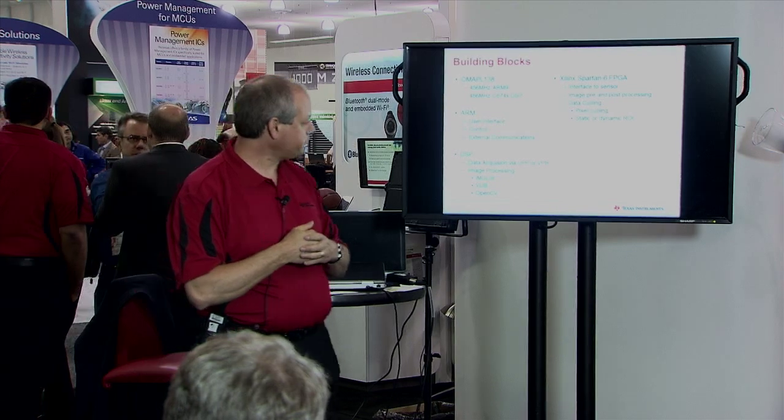So you can run about 150 megabytes per second into the UPP interface, right into the DSP and the ARM. You can direct DMA that data right into SDRAM without processor intervention. So it's a real handy interface, and a good interface for interfacing with programmable logic and other devices that have a parallel interface.